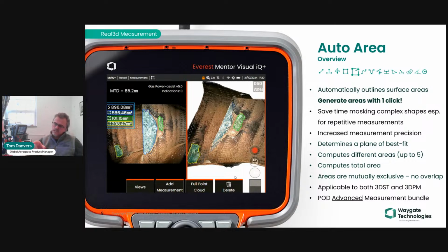And you'll appreciate, this is a snapshot image of oxidation of a part in a gas turbine on an HP nozzle guide vane. Perhaps some of those that are joining here or listening to this will appreciate it is the leading edge of a nozzle guide vane aerofoil. And you've got essentially 3 areas of erosion on this image.